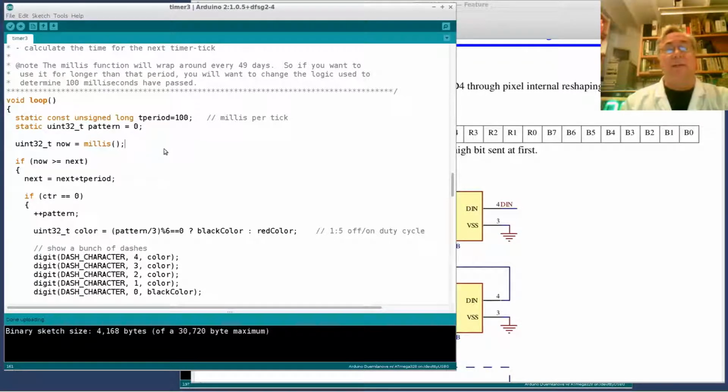The timer code makes a lot of sense anyway, because if you look here, what we're really doing in this loop is saying, look, out of every time the millisecond timer is updated, I only care 1 out of 100 times. The clock is running 100 times faster than we need it to go. So why bother? If I simply ran the clock at the speed that I wanted, it would go very slowly, at 10 hertz instead of 1,000 hertz.